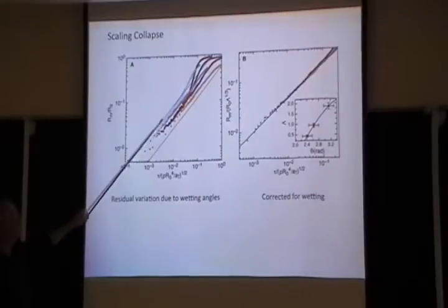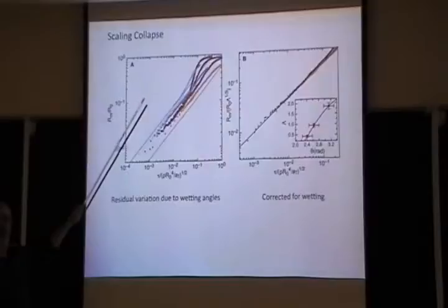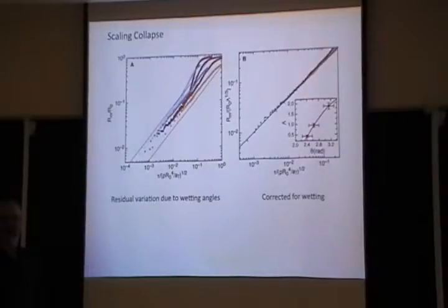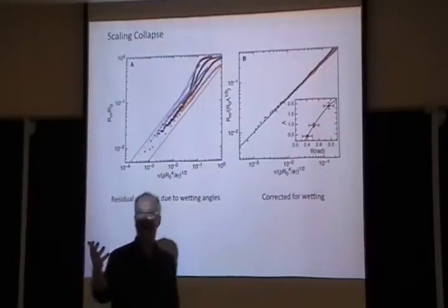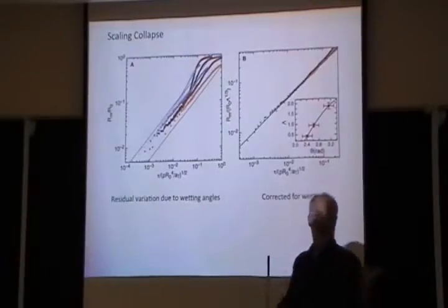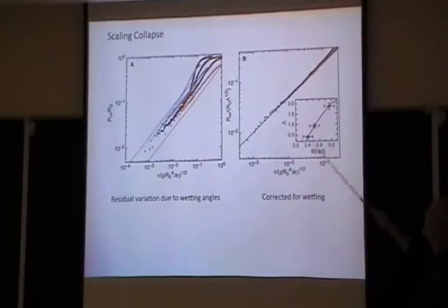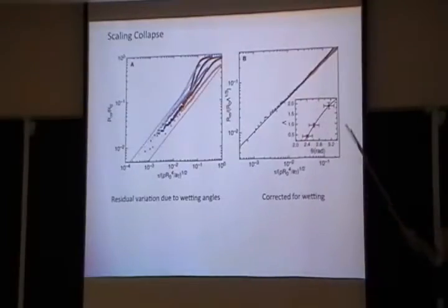And if you scrutinize it, you find out it has nothing to do with different viscosities, sizes, nozzle diameters, but it has to do with chemistry. So particles that are glass with water, oil with glass, whatever, they lie in different bands. What that says is that the alpha parameter in front of the surface tension depends, of course, on the wetting angles, right? You call it lambda, sorry about that.